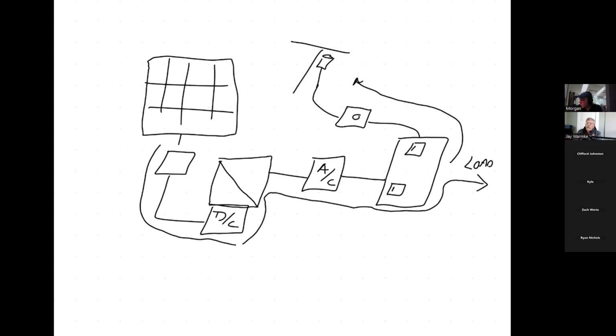So in order to deal with that, I forget which code cycle it was, but they began to require that you have a smart inverter. And that's where you get into the 1741 SA, right? Because the certification for inverters is 1741, UL 1741. Now they say SA, which is smart addendum, supplemental addendum, whatever, but it's for smart inverters.